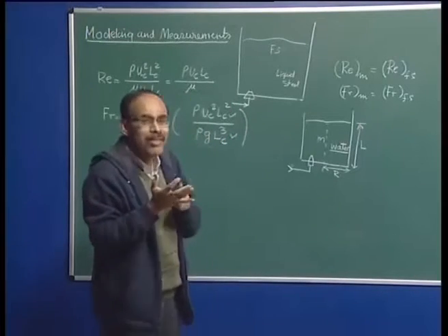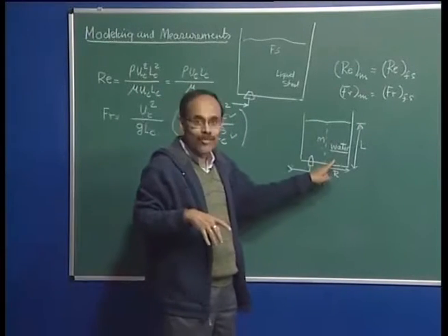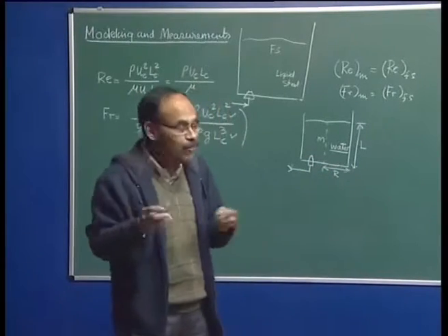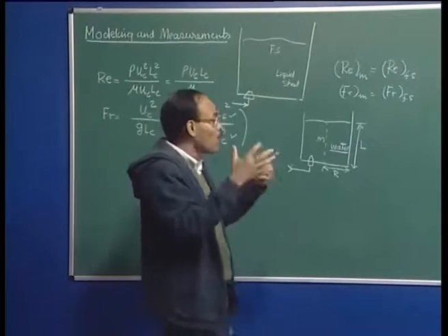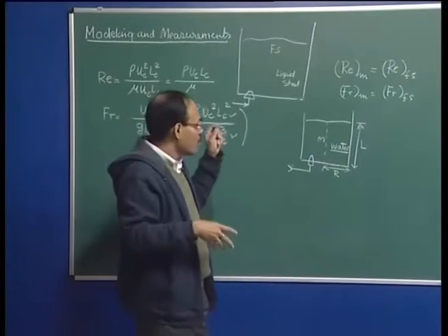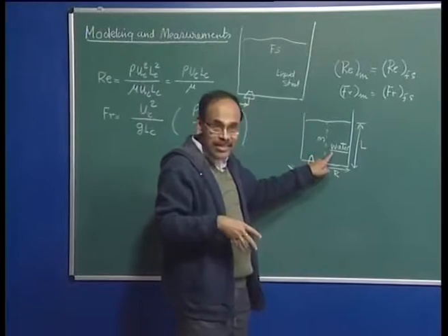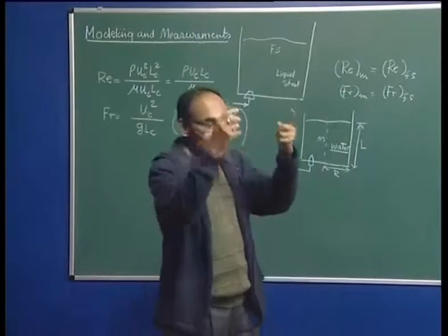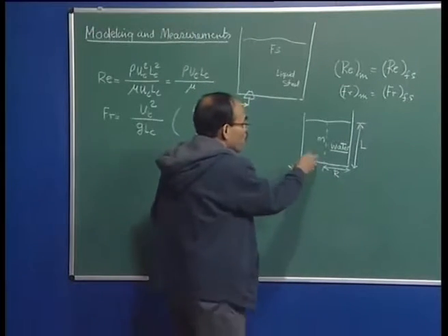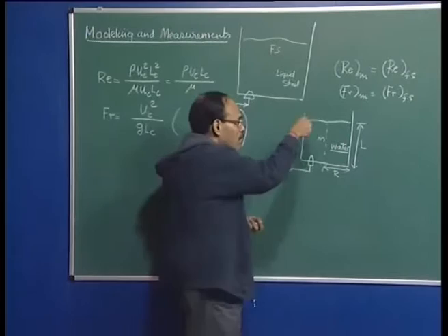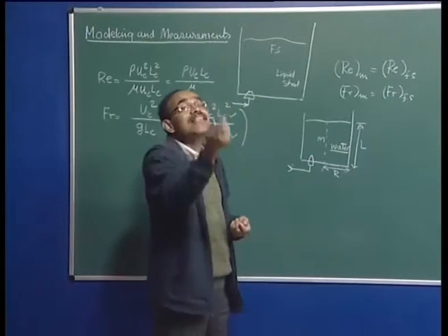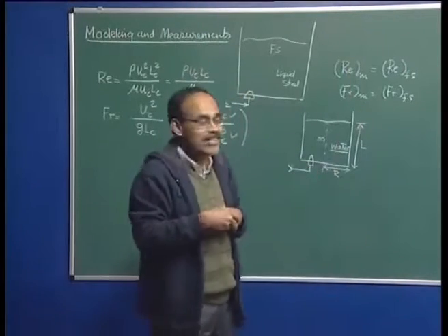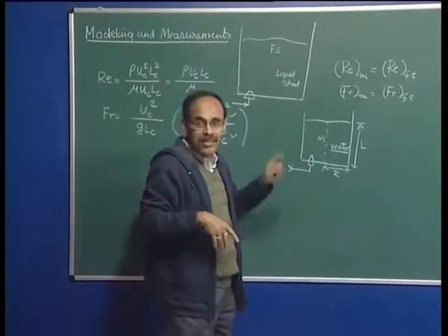The first advantage is that water is a cheap liquid. The second advantage is that it is non-corrosive, a non-hazardous liquid, and the third, from the viewpoint of studying the process, it is extremely important to recognize that water is transparent. So, we can very conveniently observe the flow pattern physically. For example, if the flow is there and I add a drop of potassium permanganate, then I can see how the color distributes, and thereby I can very clearly see what the flow pattern in the system is because of this kind of gas injection through a porous plug.